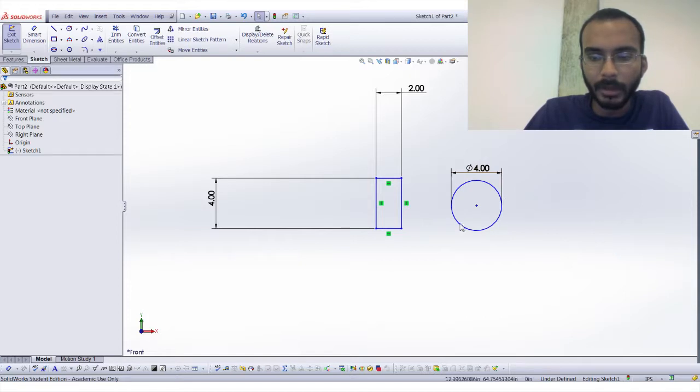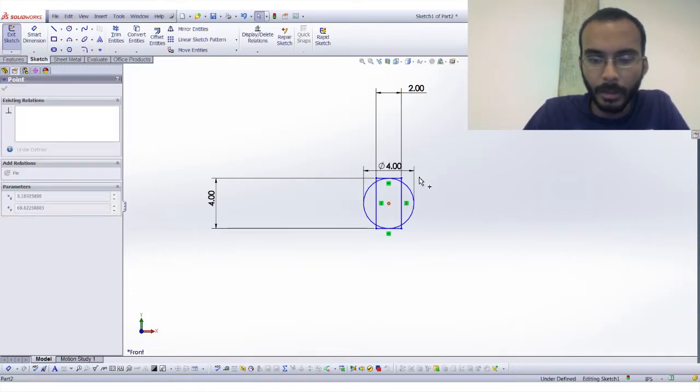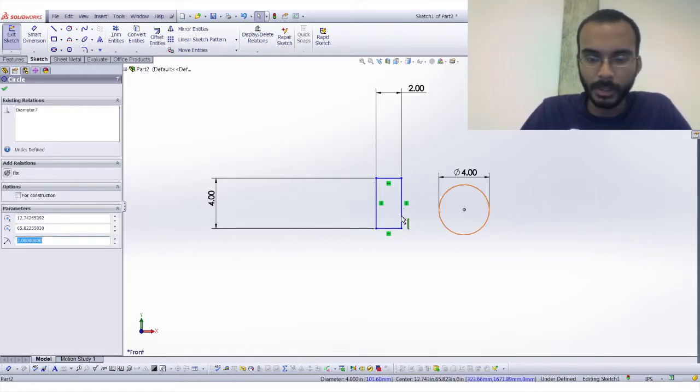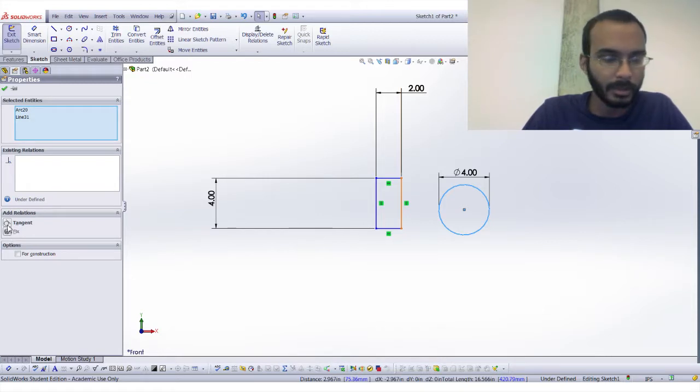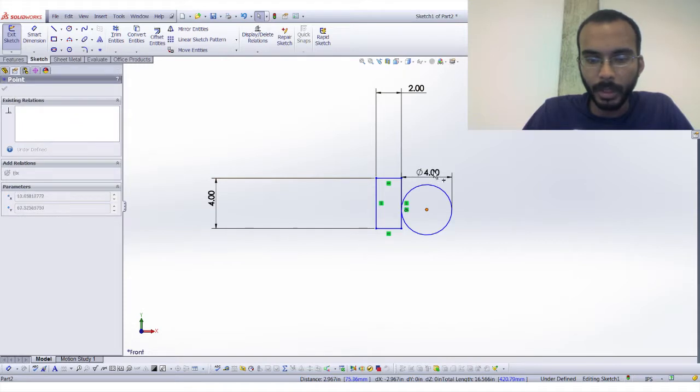Let's see, what else did we not talk about? When you are sketching, if you drag a part around, it'll snap to different points. So if you want to put something on the corner, or if you want to move it differently, you can. It'll try to give you center lines. These little dash lines that it drags out will show that you're centered with that rectangle. So you can drop it in the center really easily. Again, if you click on 2 different things, you can make relations between them, so we can tell them that this circle and this line are tangent. And then when we move it, we can't move it too far, or the box comes with us now.